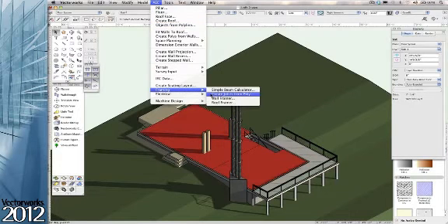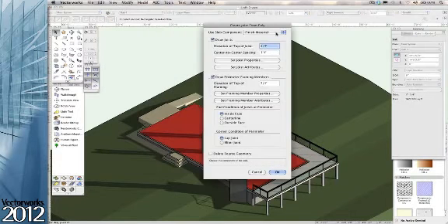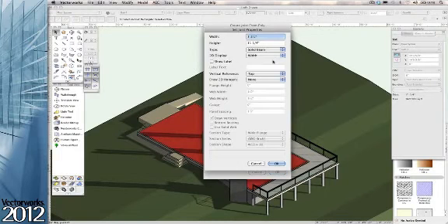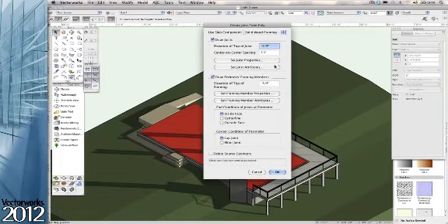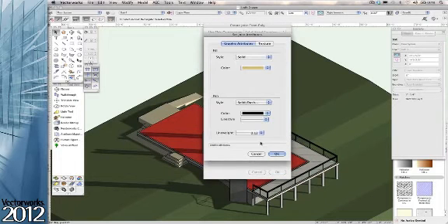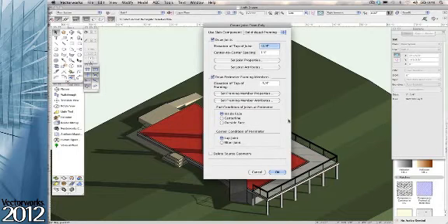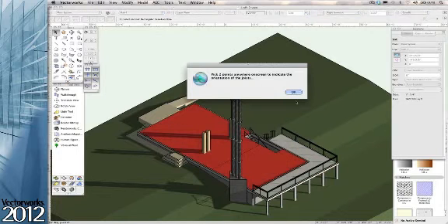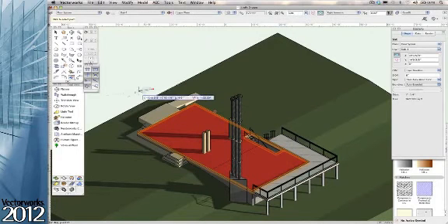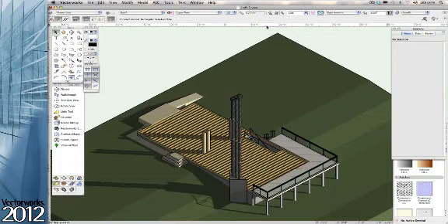Using the familiar Create Joist from Poly dialog, you see a new option at the top which will give you the ability to choose the joist gallery based on your slab style. Enter parameters for joist size, and color and texture and line weight, and then tell Vectorworks in which direction you want the joist set. The proper elevation will be automatically determined, and there you have it.